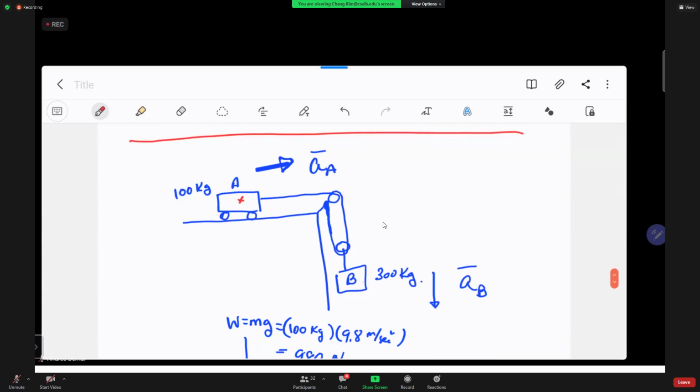The A and the B are somewhat dependent on each other. The position, velocity, and acceleration depend on this cable. The length of the cable is not going to be changing. The length of A plus the length of B, but in this case it's the two of them. So the acceleration of A, I'm going to go ahead and do the double dot here.